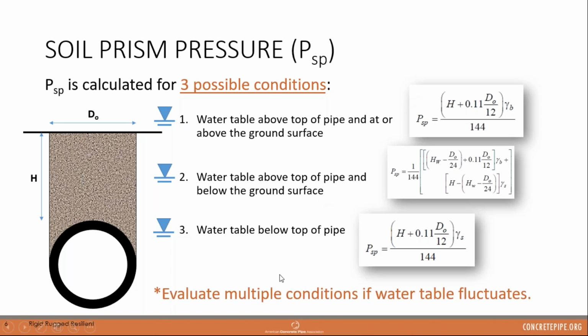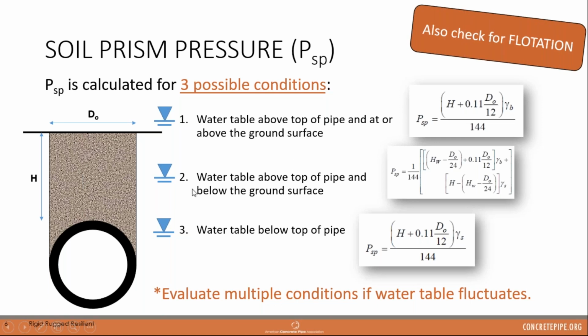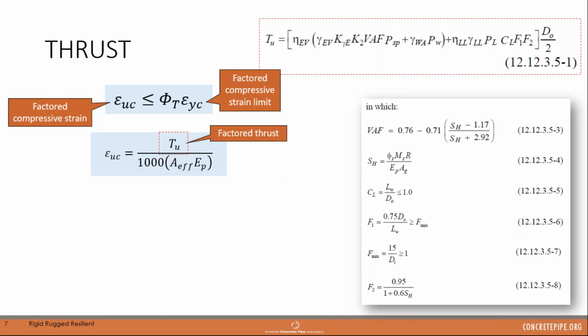Last note, again, we need to check for flotation if we do have a water table that's above the top of the pipe. Again, that's not covered in LRFD. But there's other manuals that should be able to point you in the right direction.